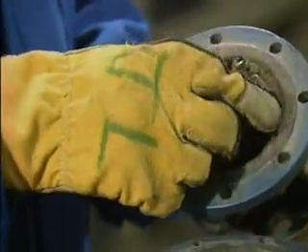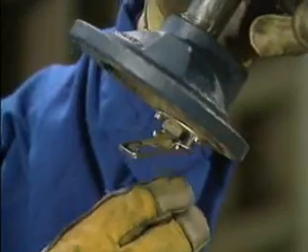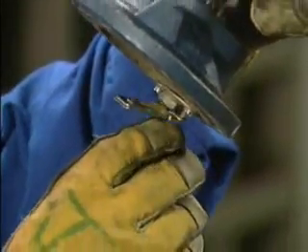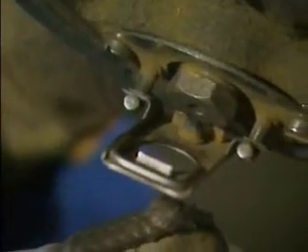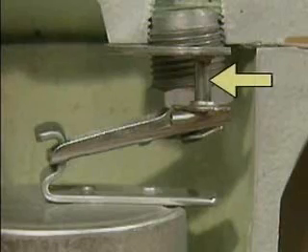A leaking trap valve is a common problem that can cause an inverted bucket trap to fail. The leak is often the result of damage or wear on the valve or the valve seat. If the valve doesn't seat properly, it will leak, and the trap may fail open, that is, with the trap valve in the open position. The trap will also fail open if the bucket becomes disconnected from the rod that connects it to the trap valve.